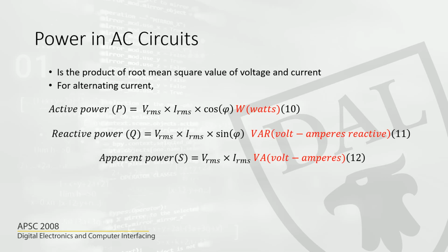So how do we calculate power in an alternating current circuit? For calculating the active power, you need to know this is the power factor. So when we say the current leads or lags, this is the phase angle which we talk about. So cos phi. For most of the problems, we give you the value of cos phi, the power factor, and if not, the angle will be given. So you can use that to calculate and multiply that with the power to calculate the active power.